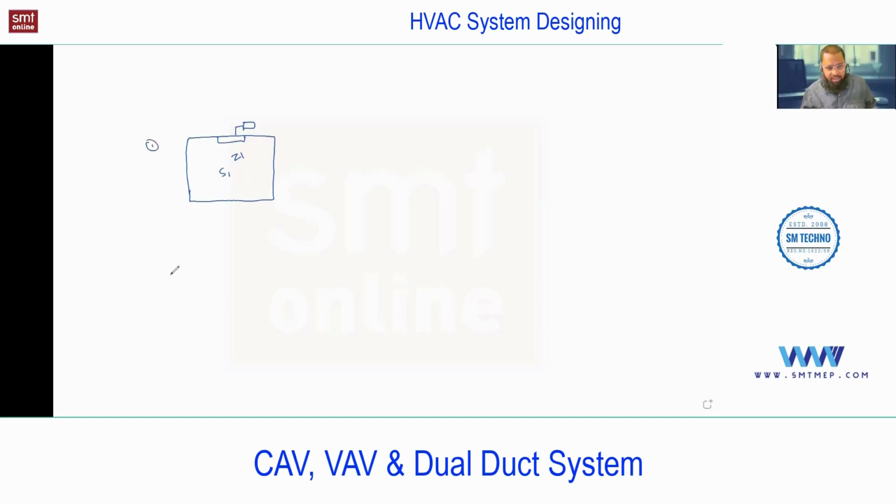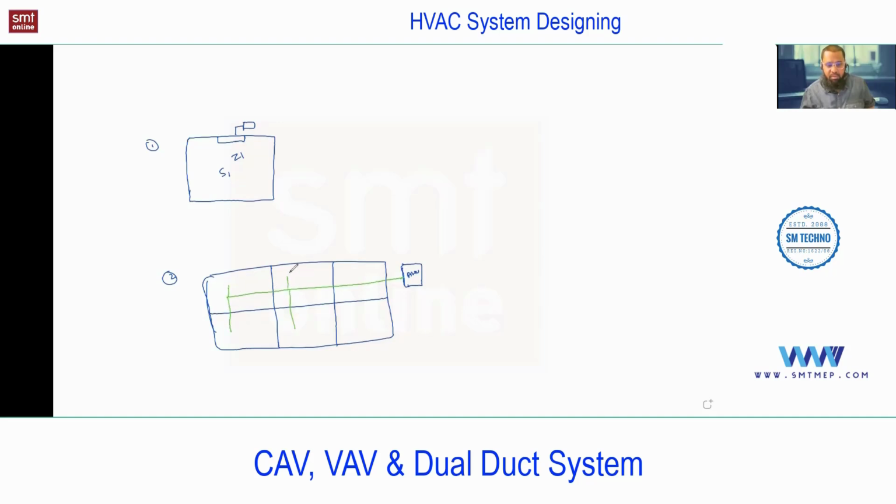Second case, for example, say multiple spaces. To all the spaces, I'm going to supply the air with this AHU, and I'm connecting the duct. Through the duct, air is going to supply through the diffusers. These are the branches and diffusers. So how many spaces in this case? 1, 2, 3, 4, 5, 6. So spaces are 6. In the first case, space is one number only and zone also 1. Here number of spaces is 6, but number of zone is only 1. Why? Because only one controlling through this thermostat.